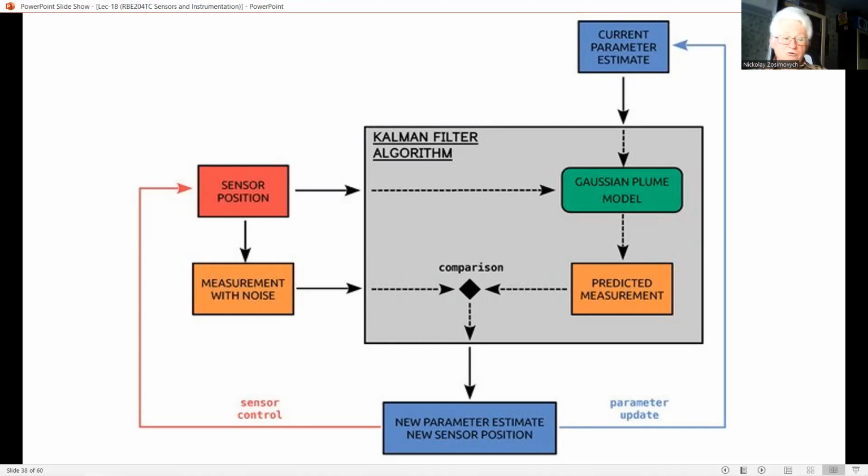And third, output measurements. As noted earlier, a general Kalman filter uses a predictor-corrector approach, which consists of the following two steps. First, predict the unknown variables and the associated error covariance matrix. This is a priori estimation.